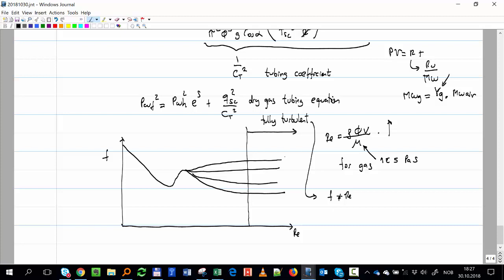If you remember, these lines had a few E1, E2, E3, E4, right? And that was the roughness for the pipe. If you look at the pipe and you see the imperfections it has on the wall, you take a closer look at those imperfections, and you take the distance, let's call it E. Epsilon will be E divided by the diameter, the roughness of the pipe, but in that case, just a dimension.